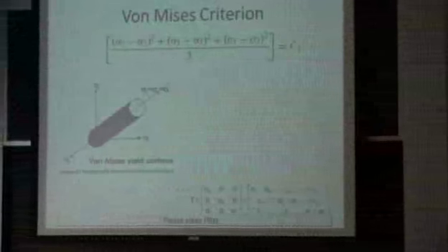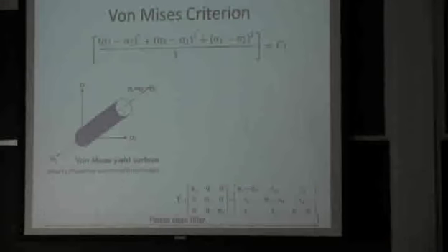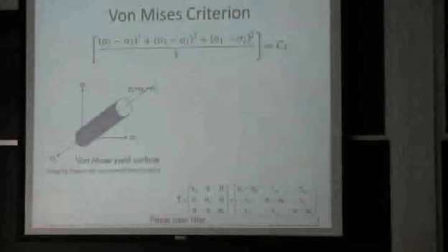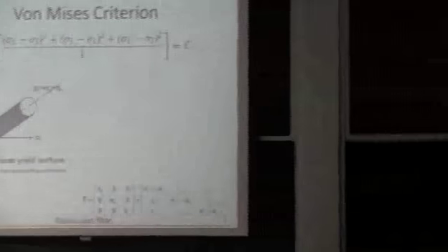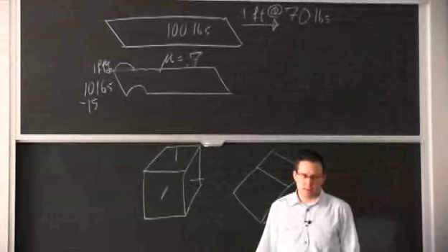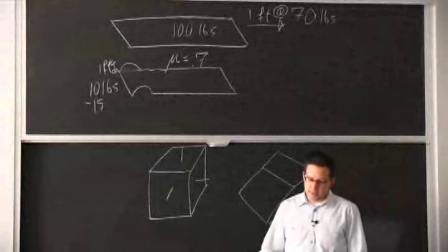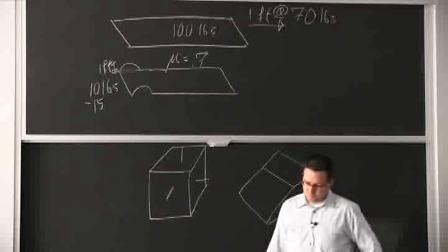And as you can see on top here, that's what he's put up as the key equation. He says if I have enough difference between the square of my differences here between the top face, the side face, the front face, I'm going to have yielding. I'll reach the yield point on the curve in 3 dimensions. So this is all very general 3D.